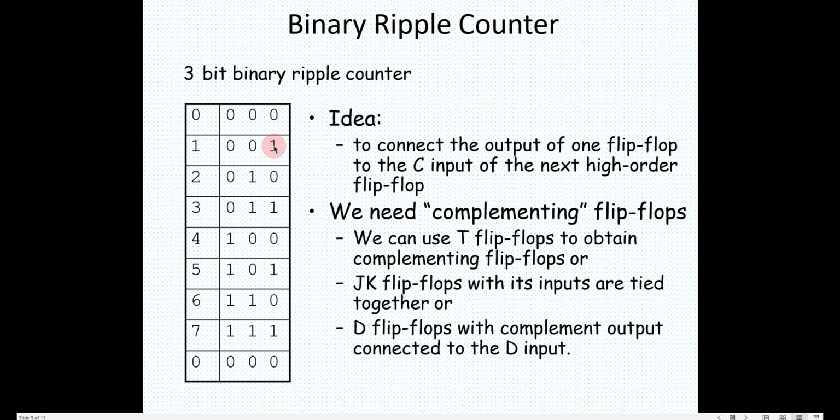With every count pulse, this is going to change from 0 to 1. So I can use a T flip-flop here. Now I have to decide what is the clock which I require to be given here. Till when we learnt about the synchronous counter, we were assuming that the clock is going to come here, and what is the T input which we have to give. Here the design is different. We are going to use T flip-flops, and both are already wired here. Now what should be the clock input? That is what we have to decide here.